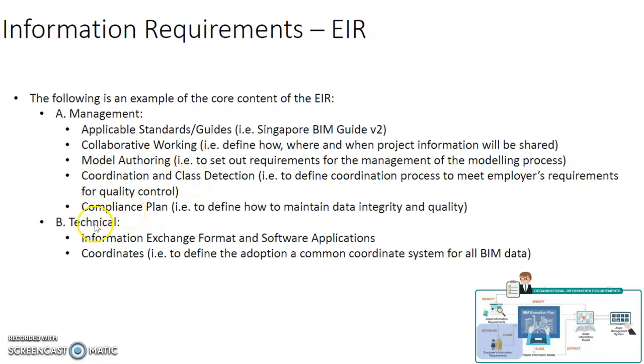Or to have a compliance plan. In the technical area, you'll be looking into the information exchange format and the software applications which I've talked about previously, or even the coordinates for the different models, because the different stakeholders could be building different versions of the required model for their work. So the coordinates must be the same set of coordinates. If not, the models will not be able to work with each other. This could be some of the requirements put down in the employer's information requirements.